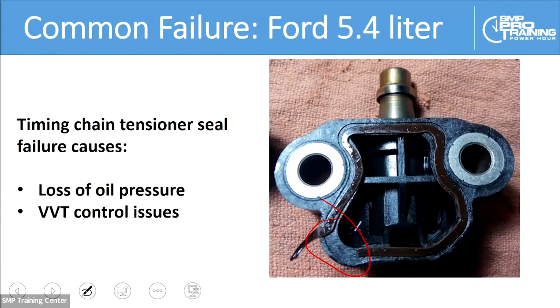And something else that actually occurs very often when you have this problem is that since we have this oil pressure being hemorrhaged behind the timing cover here, we're not properly lubricating the camshaft. And there's a lot of cam bearing failures that you'll see as a result of this right here.